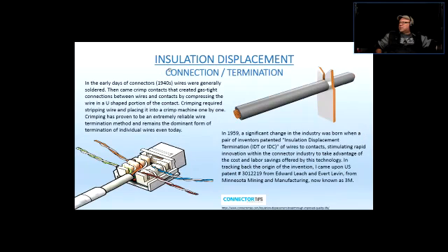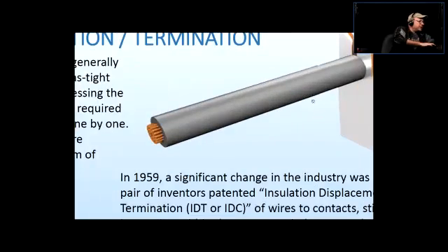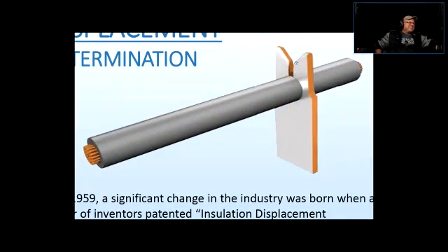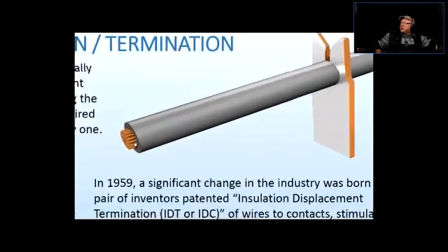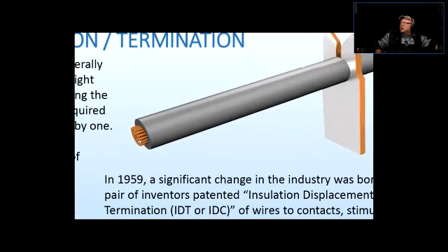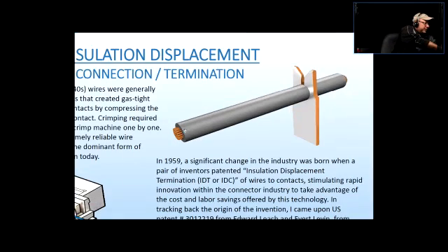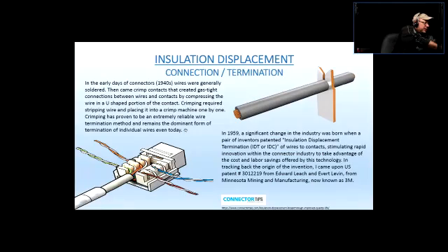Now, insulation displacement connection, we talked about that. Here's a bit of a history spill. This is how the insulation displacement connection works. It has a knife-shaped connector, and you punch in the wire, and the connector bites into the insulation and makes a connection with the wire. The only thing is, I got this image from the internet, and you don't use that on stranded wires. It has to be solid wires. So somebody put it up on the internet by mistake using a stranded cable.